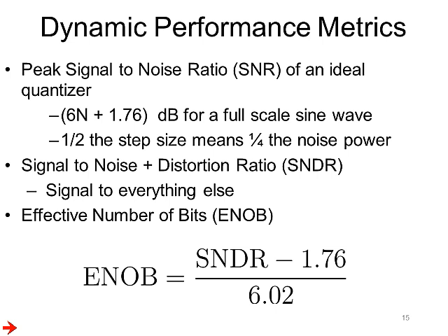The signal to noise plus distortion ratio, or the SNDR, is the ratio of signal power to everything else, and when you have a real quantizer, you'll often see this number floating around. It's the ENOB, or the effective number of bits of the quantizer. And this is computed by backfitting ENOB from the SNDR formula and is given by SNDR in dB minus 1.76 divided by 6.02.